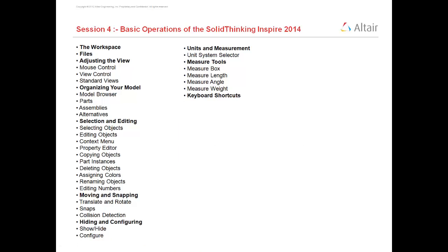In today's session we are going to see the workspace, files, adjusting the views, mouse control, view control, standard views, organizing your model browser, parts, assemblies, alternatives, selection and editing, selecting objects, editing objects, context menu, property editor, copying objects, part instances, deleting objects, assigning color, renaming objects, editing number, moving and snapping, translate and rotate, snap, collision detect, hiding and configuring, show and hide, configure, units and measures, that is unit system selector, then measure tools, measure box, measure length, measure angle, measure weight, and keyboard shortcut.